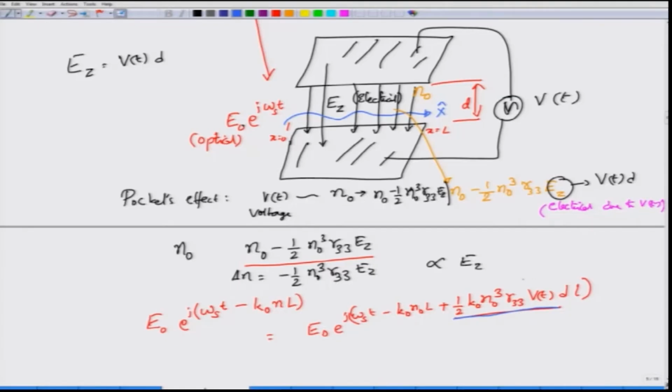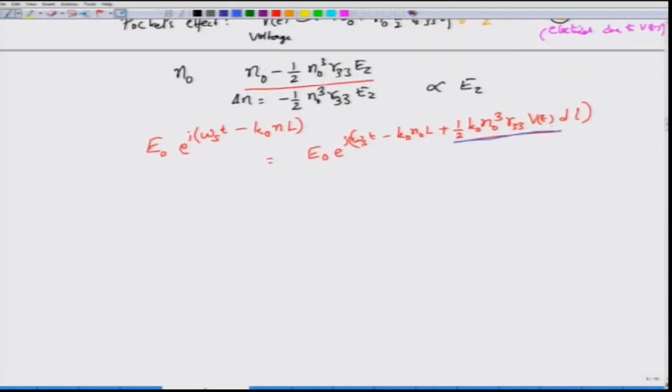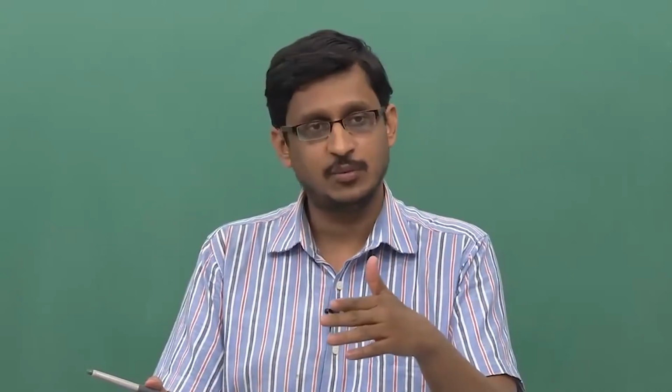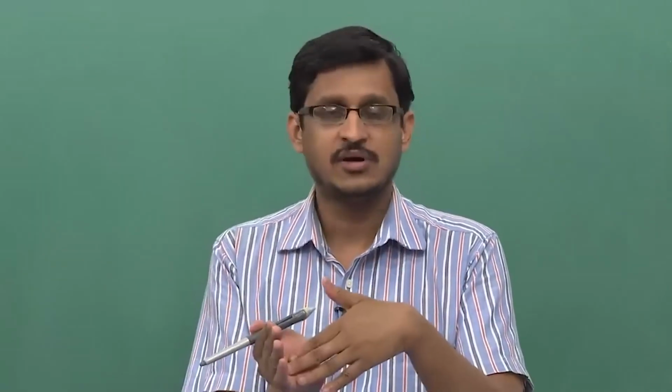So, there is just a constant phase shift, there is nothing you can do, just happily go home without constructing a phase modulator. But now you have a situation where your phase is varying with time because you have applied a time varying voltage V of t and managed to introduce a phase shift into the optical wave itself. By applying a voltage V of t, you generate an electric field. This electric field will influence the refractive index, and that refractive index change when the optical wave observes it will lead to a phase difference, okay, or a phase shift which is now changing with time.